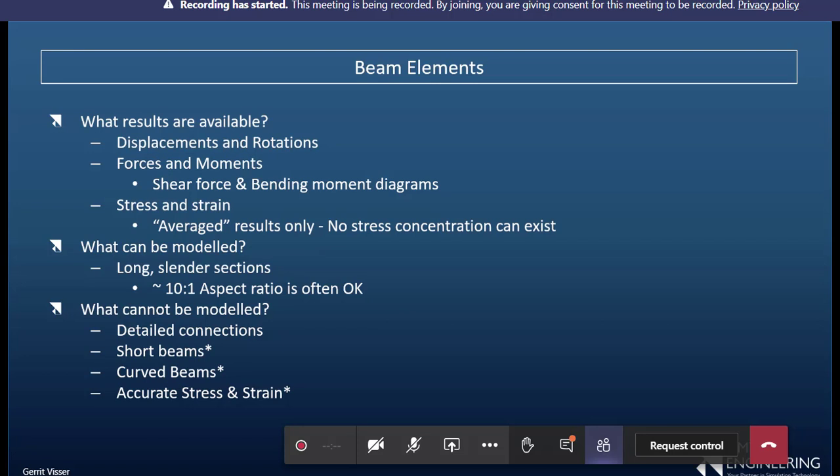So the peak value there is in the center of the beam section, and it's higher than that average that we've calculated before. It doesn't mean that average is not useful, but if I try and measure, I'm not going to get that shear stress that I'm predicting there.